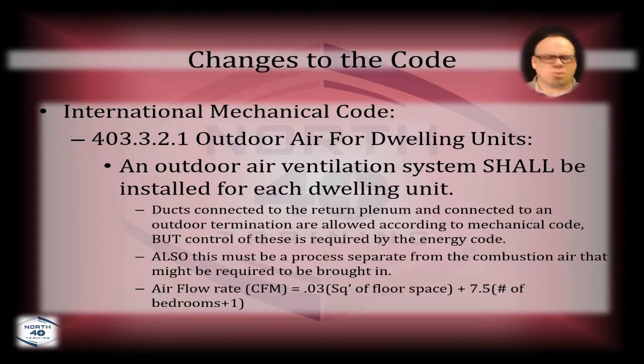And then in addition to that, bring in air for human occupancy. Well, some guys will say, why would you go through all that for the combustion air? Bring in your second pipe, your intake pipe running all the way to the furnace. That doesn't help the water heater. The water heater's power vent, it burns the air from the space, so you're still going to have to bring in combustion air to suffice that.